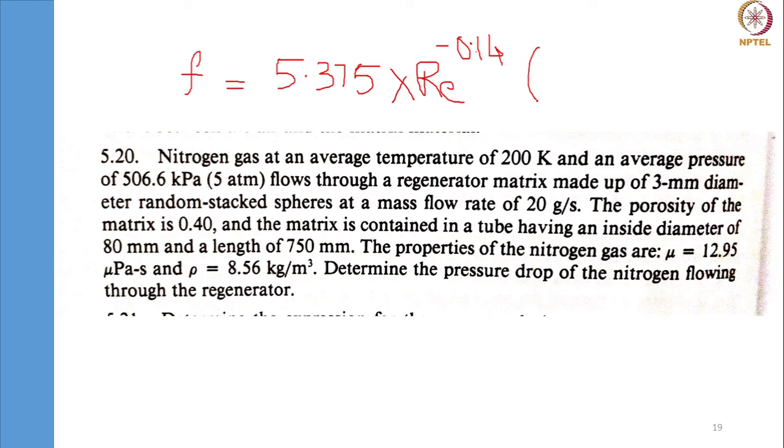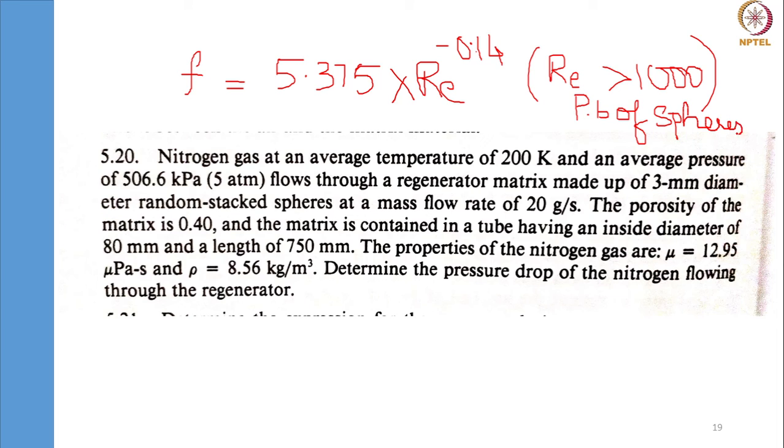This is valid when Reynolds number is greater than 1000 and only for a packed bed of spheres, because we can have different matrix materials like woven SS, woven lead, etc., but this correlation is only for a packed bed of spheres. I'll give you a couple of minutes to think over it and then I'll show you the solution.